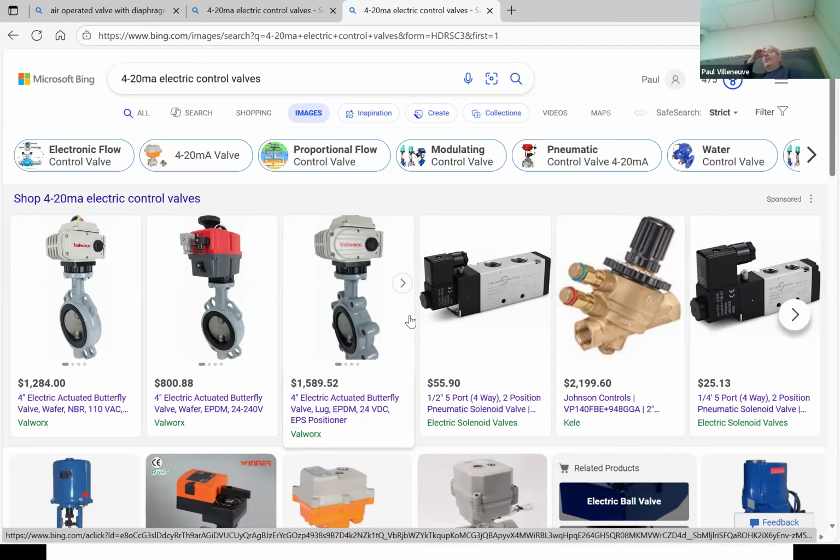Over here, no air leaks. And what's the other advantage? If your air is leaking, you get a pressure drop and you have to go find it, right? But over here, it'll tell you my wire is broken, because I should be getting 4 milliamps, but I'm getting 0 milliamps, which is indicative of a broken line. That's why we don't start at 0 milliamps, we start at 4, right? If I should always get 4 milliamps and all of a sudden it goes to 0, hey, there's a broken wire here. So you can go out very quickly and troubleshoot it.